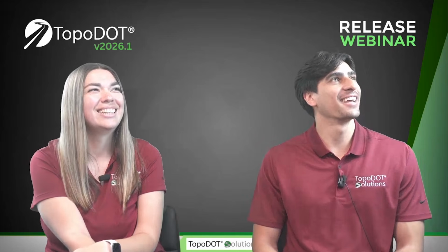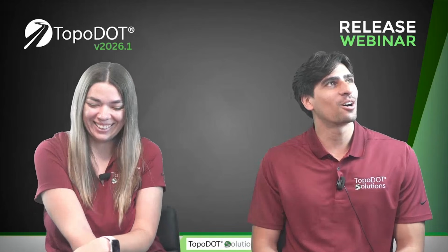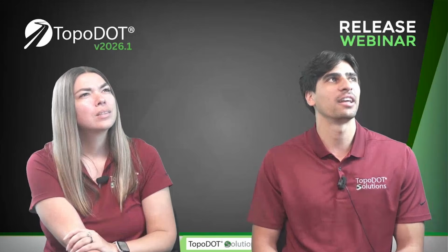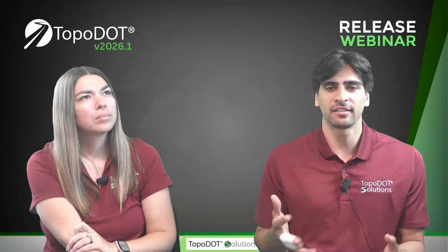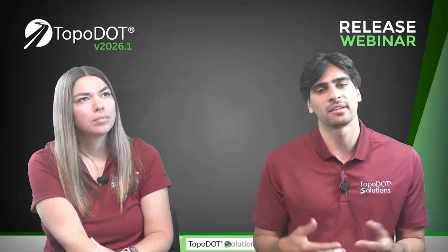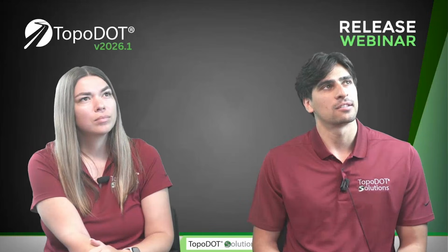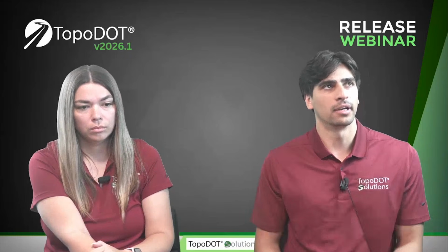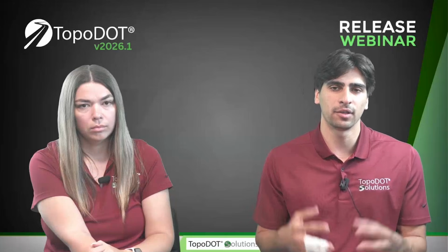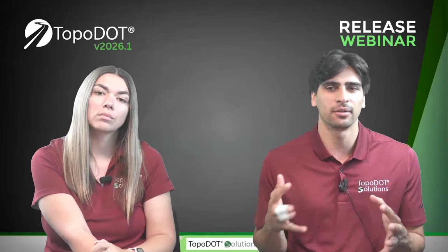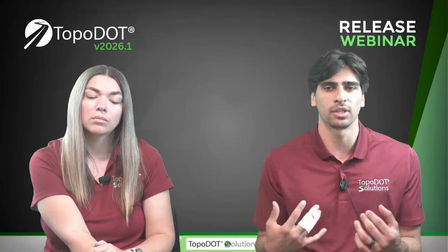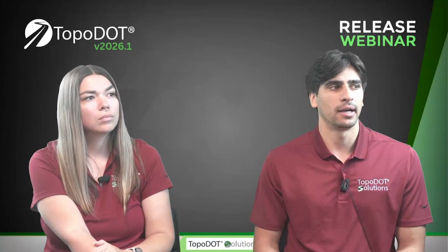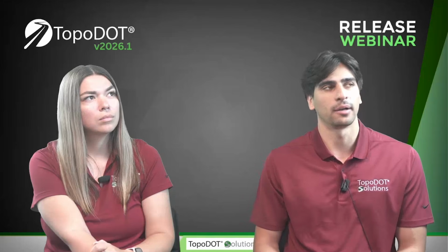Yeah, Jason's asking, can we set a toggle to make the building extract tool normalize to right or standard angles? Yes, the tool has a straightening tolerance value that you can set. So it will straighten up that line depending on a specific threshold. But if you are using that tolerance value and you feel like it's not accomplishing what you need, feel free to reach out and we can troubleshoot the issue with you and possibly add an enhancement to it if required.